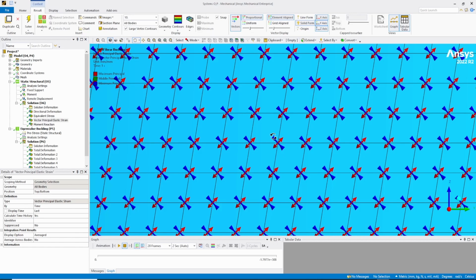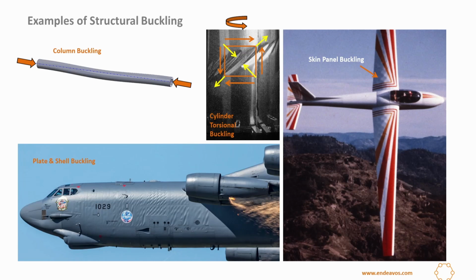So this compressive stress, along with the axial stress, which is pulling like this, causes shear wrinkling that I showed earlier, if you recall, this phenomenon here. So we have a compressive stress and a tensile stress in this direction. So this is causing these wrinkles.